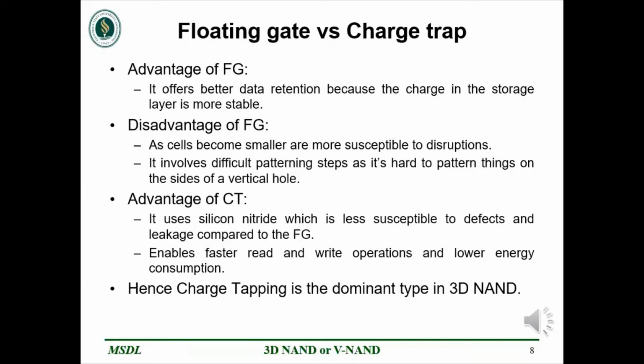The main advantage of the charge trap technique is that the silicon nitride used is less susceptible to defects and leakage. Also, this approach enables faster read and write operations, as well as lower energy consumption. Hence, the charge trap technique is more dominant.